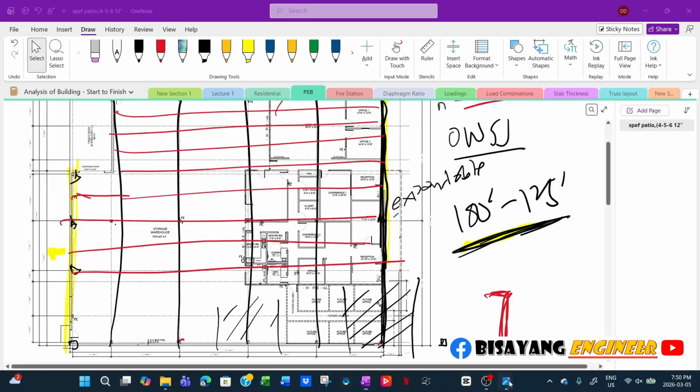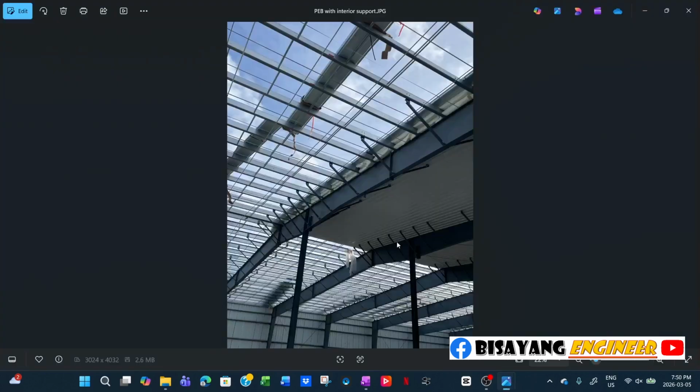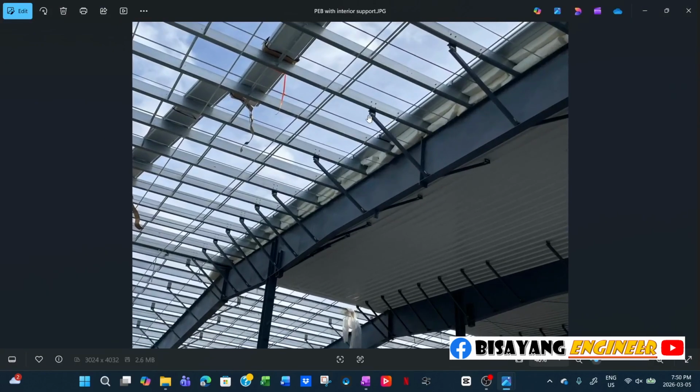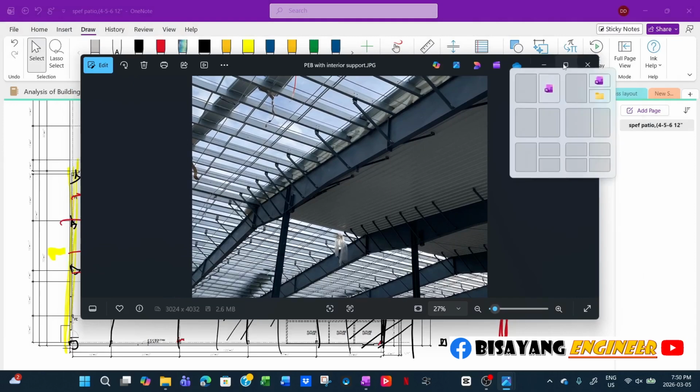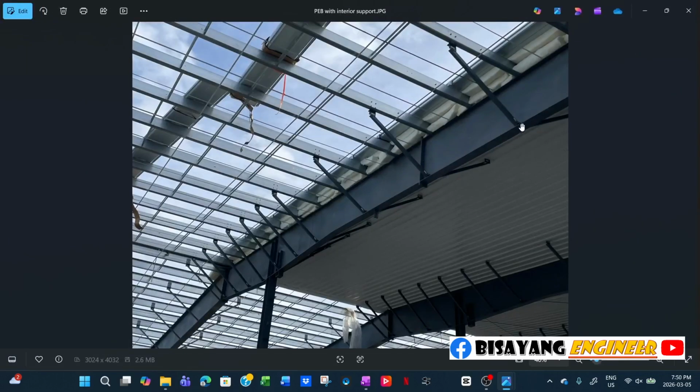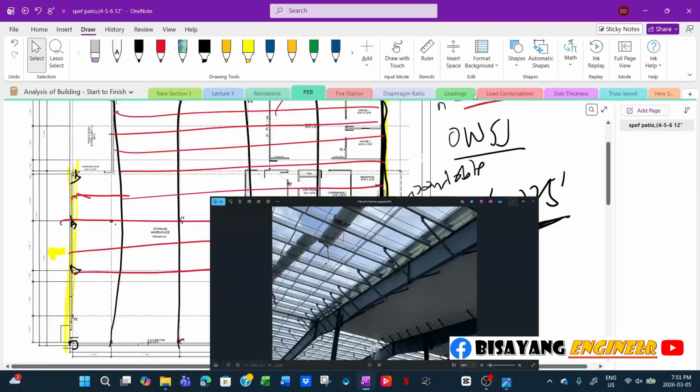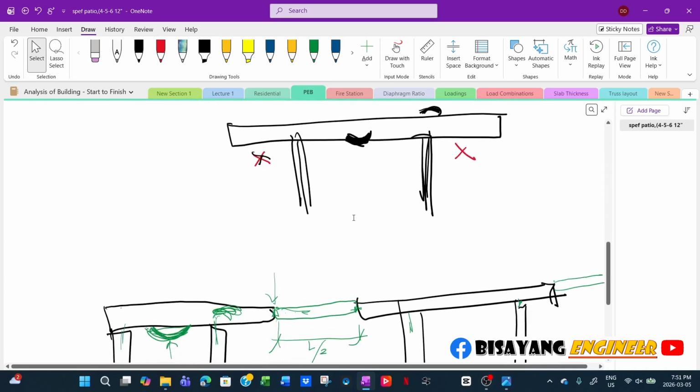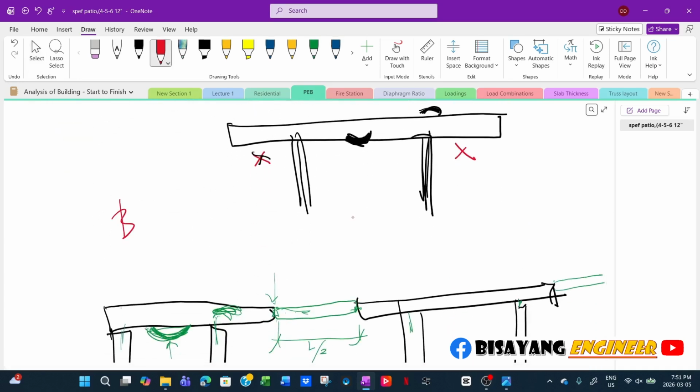In this particular picture, you will see the engineered frame, and then they have this bracing. This bracing is crucial in designing the frame, because if you provide bracing, like bottom flange bracing, you can reduce the unsupported length of your framing. Then it will be an economical size, because that will prevent torsional buckling, like local buckling.